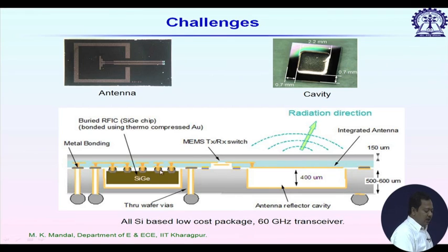Now, if I look at this chip, the passive components, typically the inductors, occupy a very large area, and usually they are fabricated on the top metal layer of the chip. So, the coupling between the inductors and the antenna is expected to be maximum. So, sometimes, to avoid that coupling between the inductor and the antenna, we use some sort of guard ring around the antenna structure, which will minimize the coupling between antenna and the inductors.